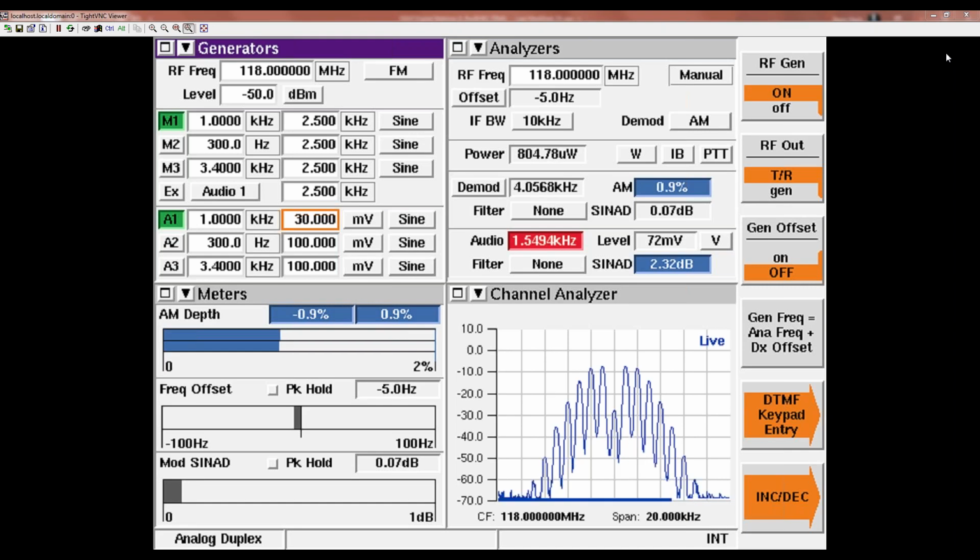Whenever I do radio seminars or live radio workshops, I quite often see people haven't used cable losses, and I don't care if it's AM, FM, or digital. Does it really matter? Well, if your cable loss is half a dB, your sensitivity is out by half a dB. But if it's half a dB in power, then it can become more significant.